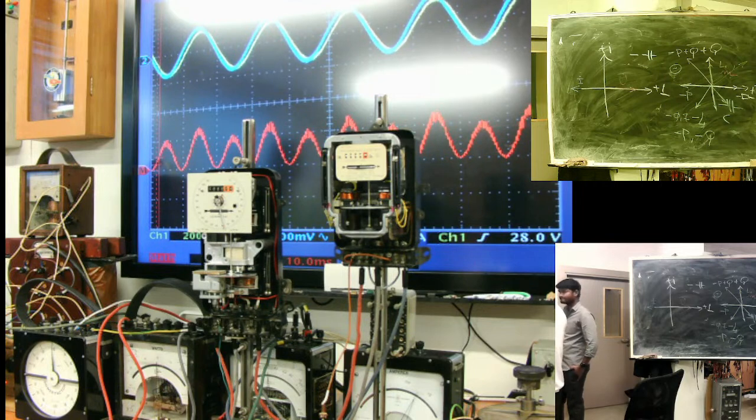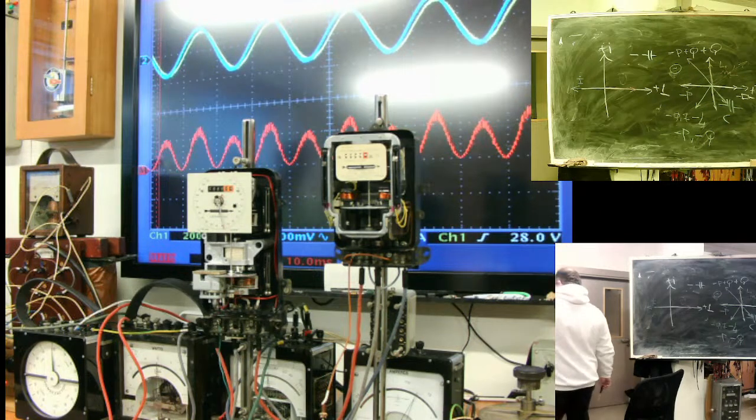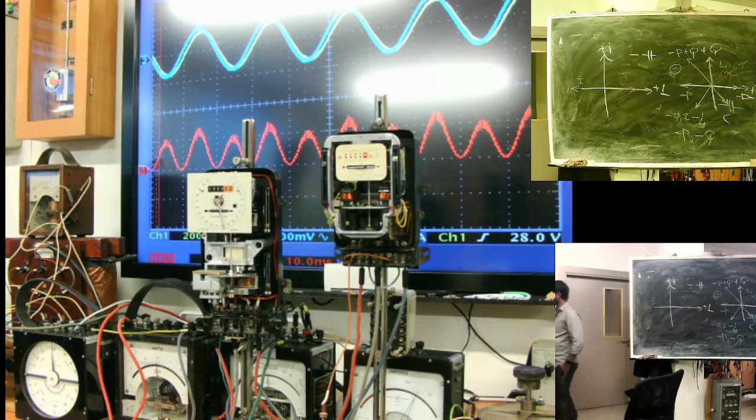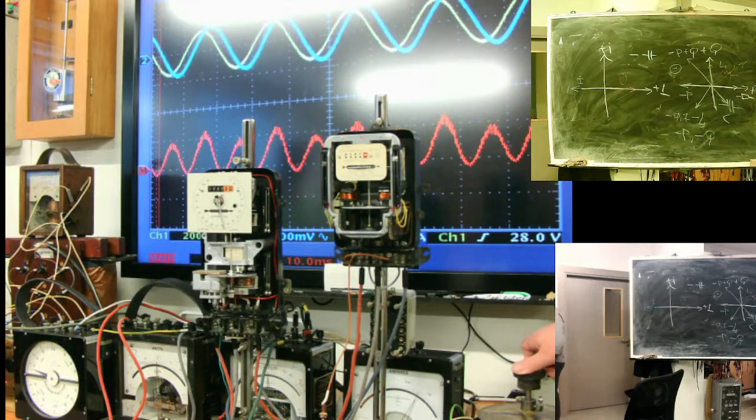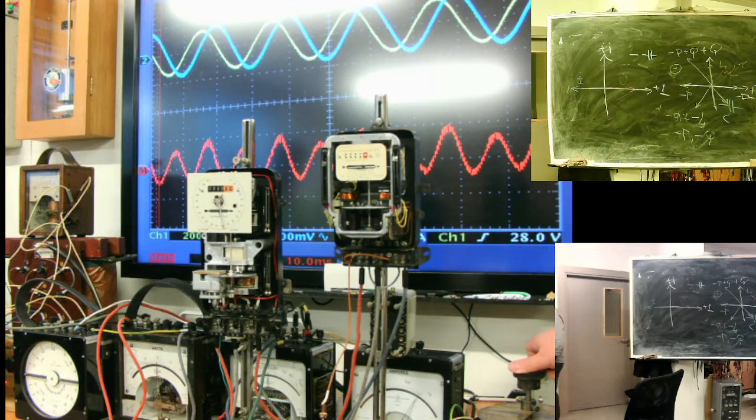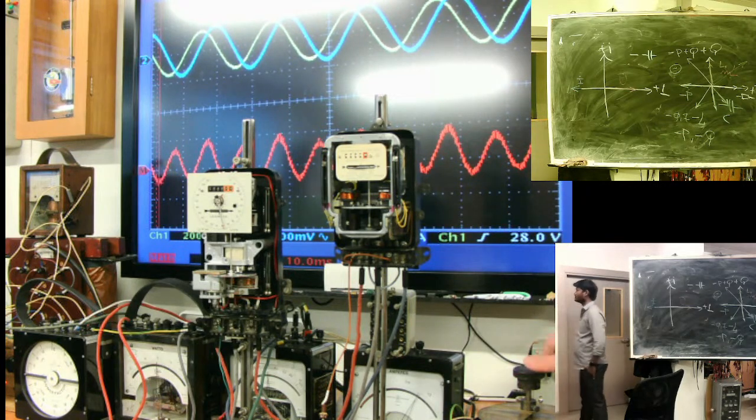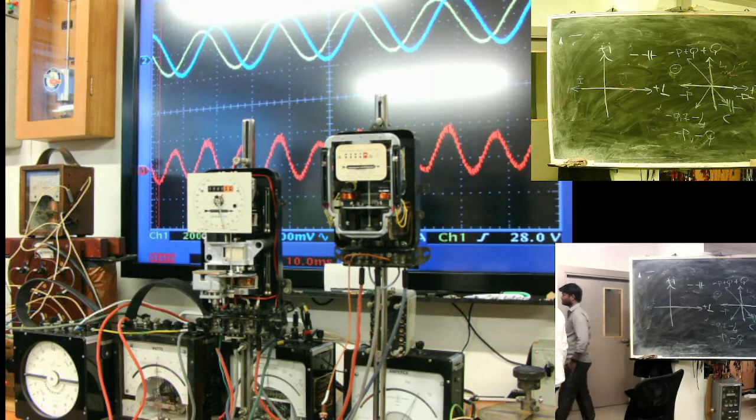Now, if you can see, I'm simulating a cosine phi 1 mode. Power factor now is 1. That means active energy flows, and you can see the first meter rotates, and reactive energy stands still. Yes. Now let's simulate what? What kind of mode? Lagging or leading?